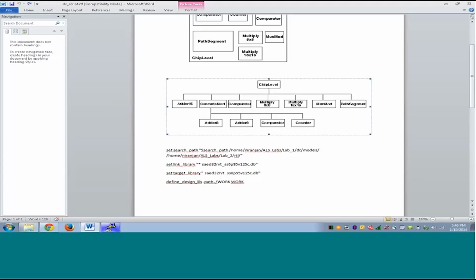You just have to make sure that inputs are registered and outputs are registered. You should have good timing constraints for inputs and outputs. Try and simplify the design for 500 megahertz and make sure that all the paths meet timing. It would be a very good assignment to have.